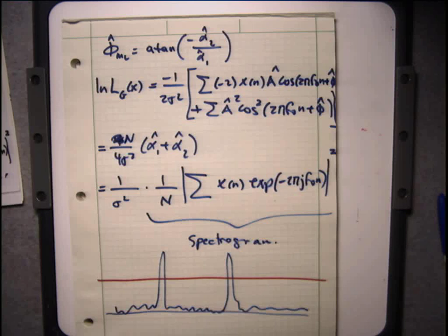And how do you set the threshold? Well, then you have to do this analysis with the performance. If you assume the amplitude is really small, for instance, then you can do a locally optimal test. Okay. Now here's where things get interesting. If you know the amplitude is positive, and you know that it's really small, you can do a locally optimal test. There's all kinds of generalizations of this that of course we can do as well.